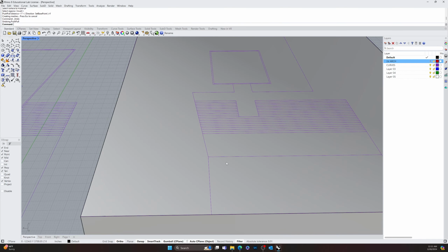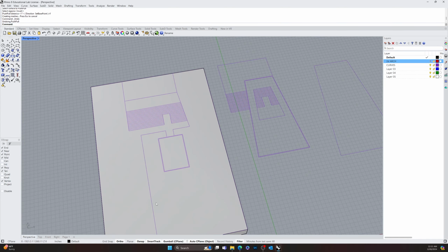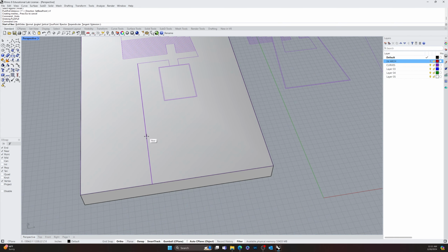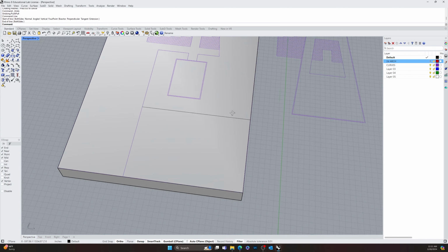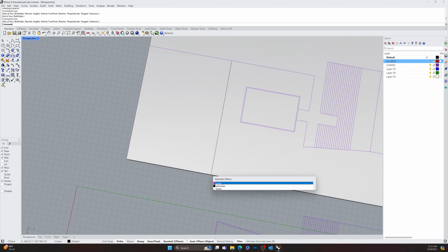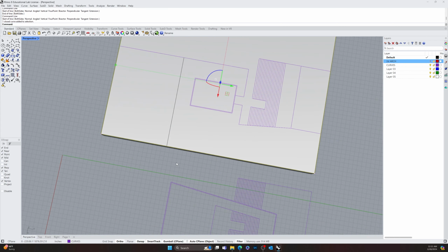So let's do this. Undo. The reflecting pool will end where? Let's end it. Make sure it's, let's do maybe midpoint on this. Where's mid? Right here. Straight across to there. Okay. And then I'm going to take this curve and let's just offset it. 5 foot, enter.